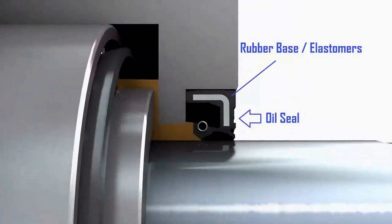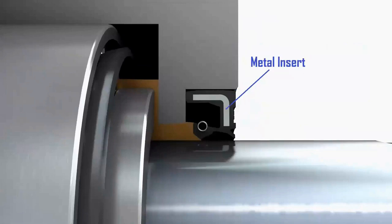Oil seal is a ring-shaped component where the main component is based on rubber and rubber derivatives such as fluoro-rubber or nitrile rubber. Oil seals can also be made from elastomers, which are plastic derivatives that are similar to rubber. Metal insert is a ring made of metal. The point is to strengthen the construction of the oil seal due to the nature of the rubber or elastomer, which tends to be elastic. The oil seal does not always have a metal insert in it.